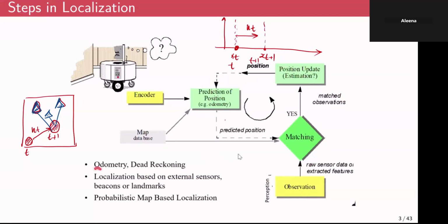the key thing that you would want to understand is something called odometry. Odometry is basically the prediction phase, right? It uses information just from its encoders. For example, if you have a differential wheel robot like this, and you have two wheels, and each of these wheels has an encoder used to measure how many times the wheel has rotated.